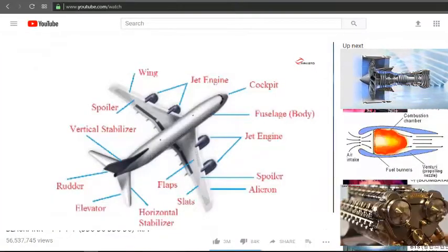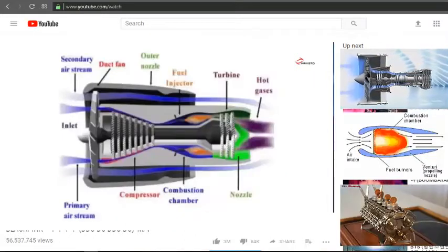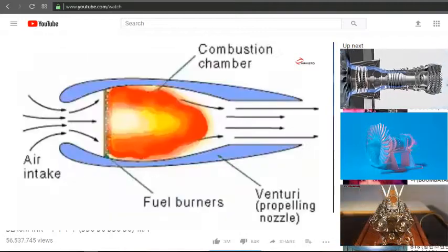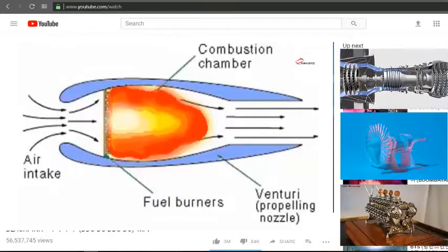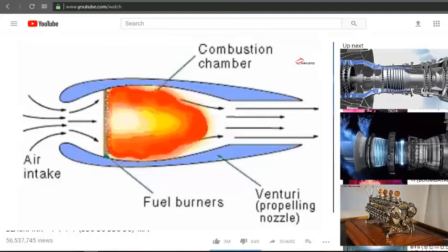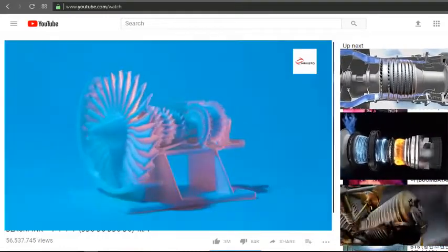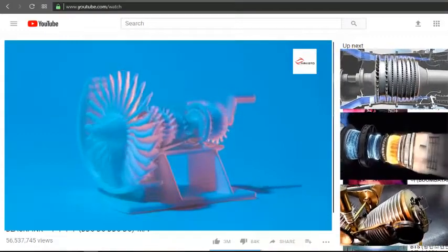This turning of the turbine also rotates the shaft to which it is fixed. The same shaft in turn rotates the compressor. Which means instead of just letting out those hot gases, they are indirectly used to suck fresh air at the same time. This is the reason we need a turbine after the combustion chamber section.